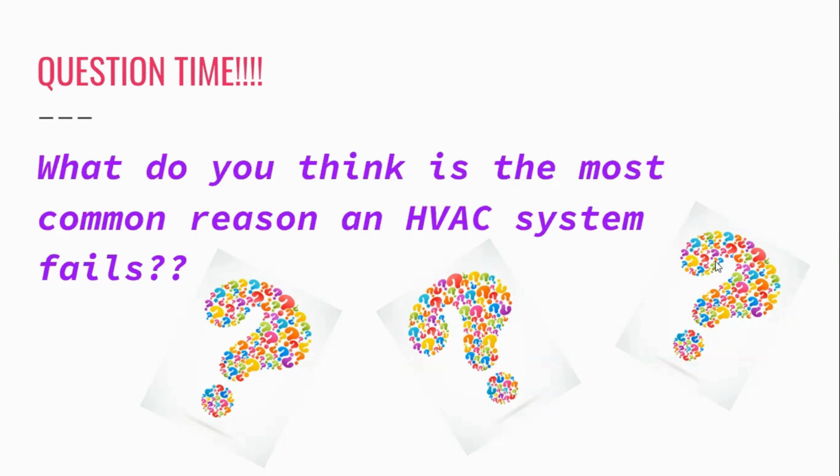You'll see them outside with banana boxes or trash piled up on top of them. You'll see a blanket over the coil of dog hair and fur. And even dogs going to the bathroom. Dog urine is high up there on reasons that HVAC systems fail, because the outdoor units are outside, and dogs don't know any better, and they end up crumbling the coils. It actually poisons the coil and turns it to acid. So yeah, that's a thing. But yeah, lack of maintenance.